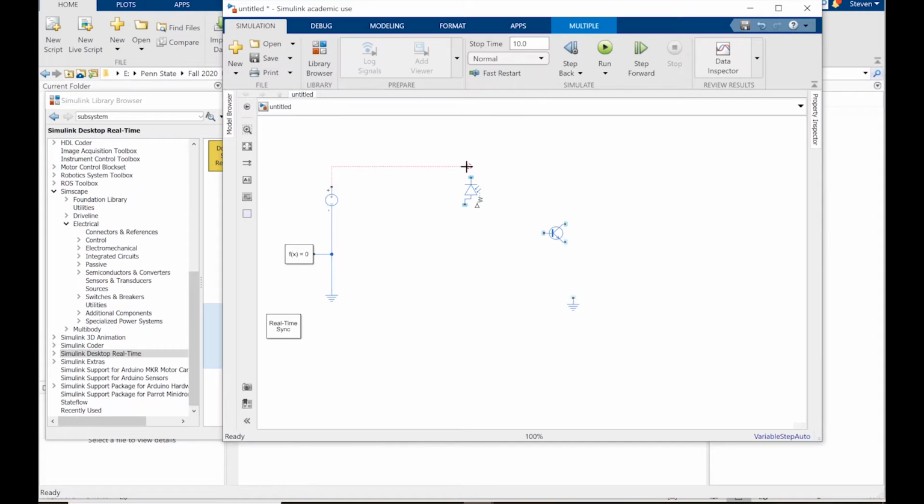And there. So this is going to be my positive VCC, and the function of the transistor is basically just a simple amplifier. So for an amplifier, I need a resistor. I'm going to use the common collector because I want a positive correlation between the amount of light and the amount of voltage. So I want a resistor on the emitter. So just left click and resistor, and Control R. 1000 ohms. Control R. Rotate that clockwise. Connect those up. And here, this is the basic model.